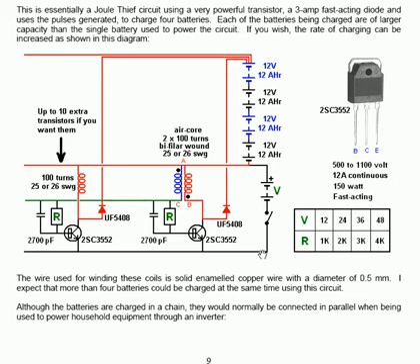Again, he has a 2700 picofarad ceramic capacitor connected across the resistor R, feeding the transistor. He does show a similar 2700 picofarad capacitor across the resistor feeding current to the second transistor, though he does say that it's not necessary to do it.